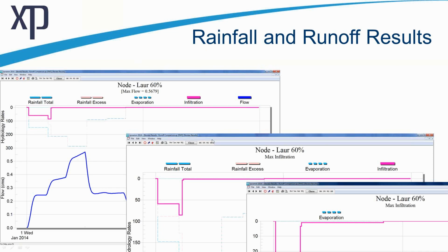For this particular graph, it's only showing about an hour and a half of time, and you might expect on any given day, even in a relatively arid area, evaporation rates in the order of 5 to 10 millimetres per day on a particularly dry day. And of course, you don't necessarily expect particularly dry days prior to or after a rainfall event.